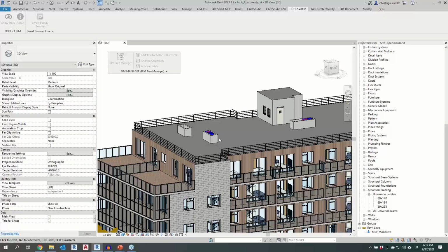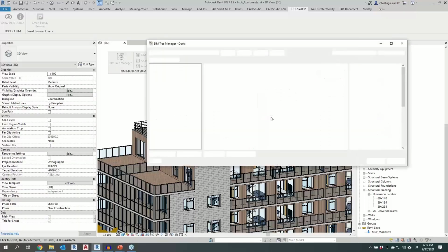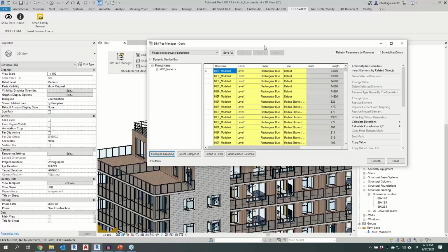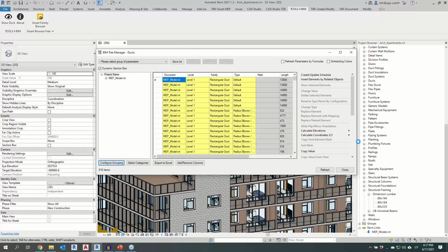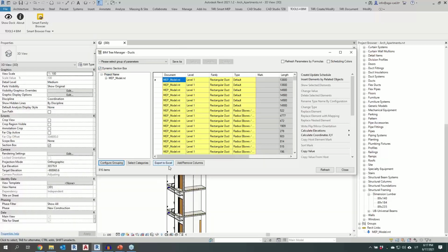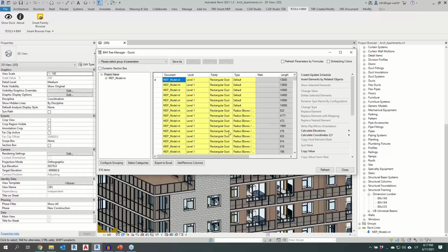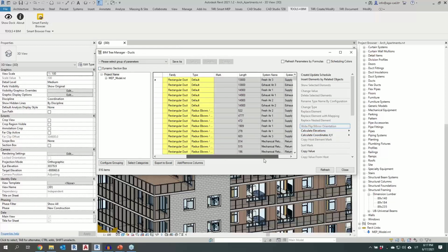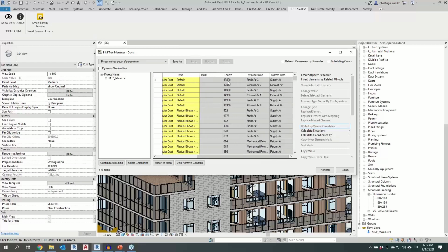And right now we will see in the same table, none of the parameters will be editable since we're seeing the linked elements, but it will be possible to select any parameter from those linked elements, see those in the table, and according to those, do filtration as we did before for previous elements. And I forgot to remove the dynamic section box, so it's actually trying to create one now. Maybe I don't want it right now. I want to show that there's a possibility to see parameters.